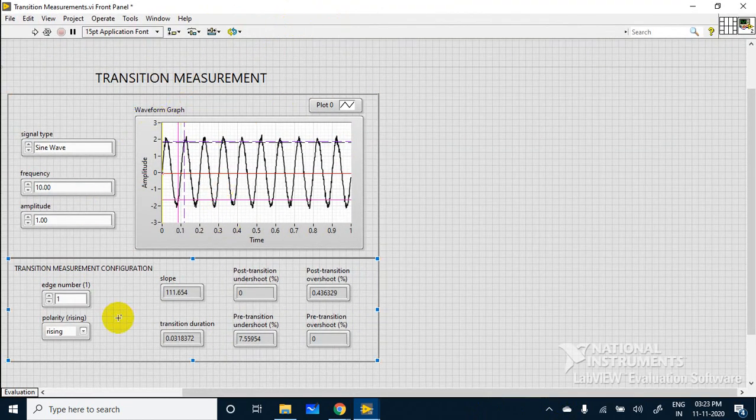Okay, and this waveform we can measure, like what type of waveform it is, sine waveform, and frequency, and what is the undershoot time, overshoot, because these are the parameters which we normally measure in a DSO, not in analog CROs. It will be DSO, digital storage oscilloscopes. It will be an automatic display, but in our LabVIEW we can create it. That possibility is available.